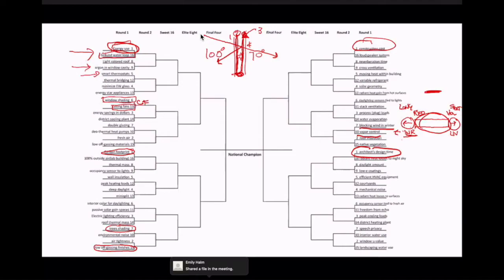And it will improve, again, it depends. In the winter it's supposed to improve, but it doesn't really that much. In the summer it will improve the performance of the window significantly, maybe 30% better at keeping out heat or something like that. But that's if the sun's right on the window. If there's no sun, you can do better by planting a tree in the right place, or building a shading element in the right place, in which case the low E coating does almost no good.